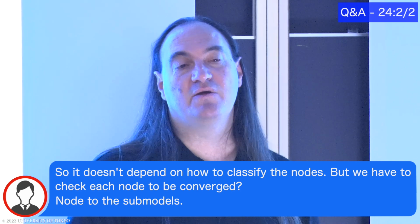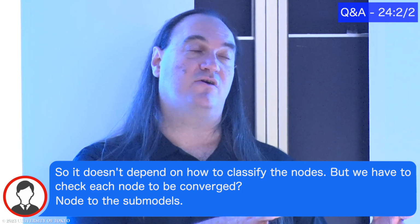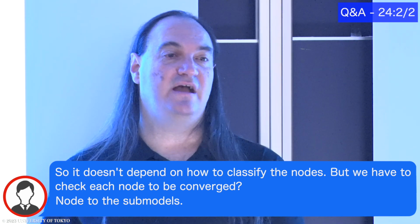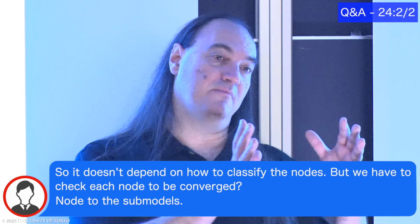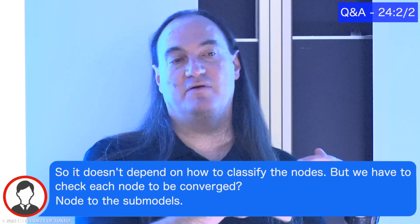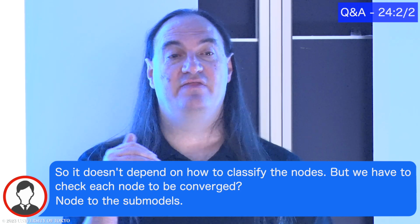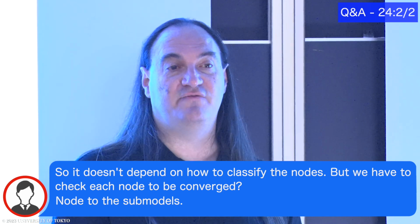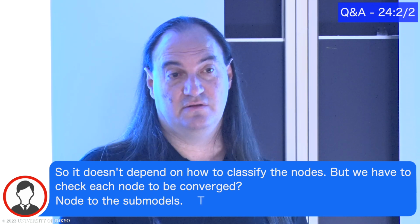The only way that it would is if I had that node and I said, okay, for submodel A, I want you to call yourself converged when you've only changed by 10 millikelvin. But for submodel B, I only want you to call yourself converged when you've changed by 1 millikelvin. Well, submodel A at 10 millikelvin will converge quicker because I can allow a greater tolerance for error than the 1 millikelvin case. So that would be the only time it makes a difference, if you have different convergence criteria for that particular submodel as far as the node goes. Okay. Clear? Back in the back.